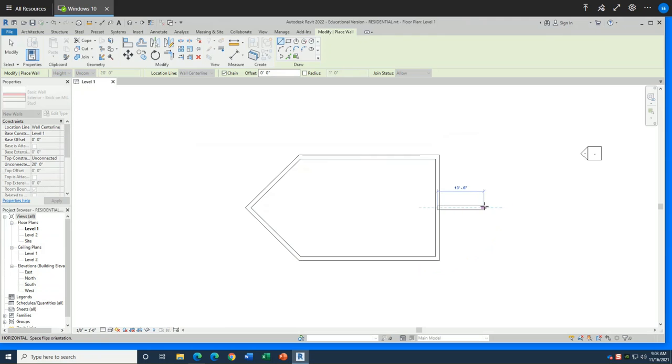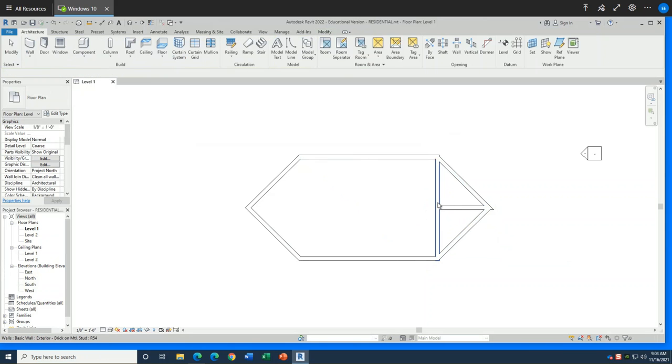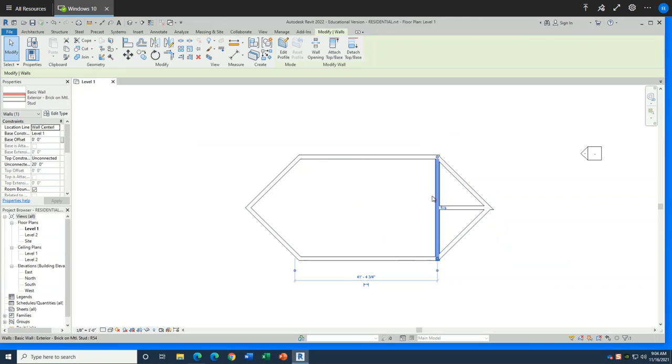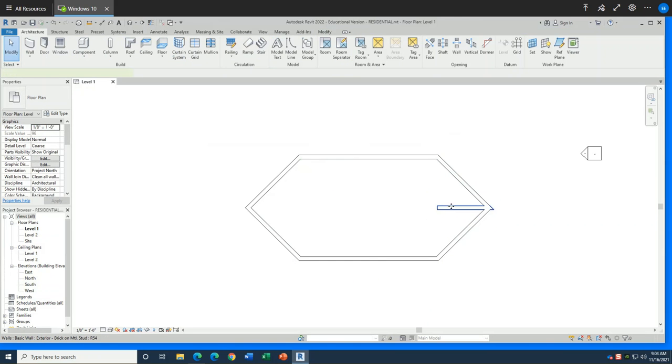We're looking for the center point. We're looking for a 15 feet long wall. And then I'm connecting this wall to the corners. I'm drawing another wall from another corner. Okay, and escape. Select one of the walls that you don't need. Select the other walls you don't need. And now you have the exterior walls of the building.